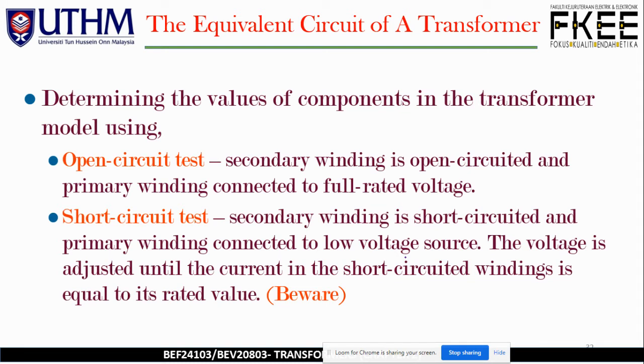Determining the values of components in the transformer model using the open circuit test and short circuit test. There are actually two methods we can use in order to determine the values of the components, for example, the REQ, the XEQ, as well as the RC and also XM. We will see it much better when we come to the exercise. However, we try to understand how the method works.